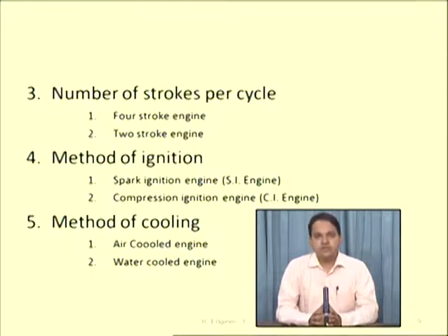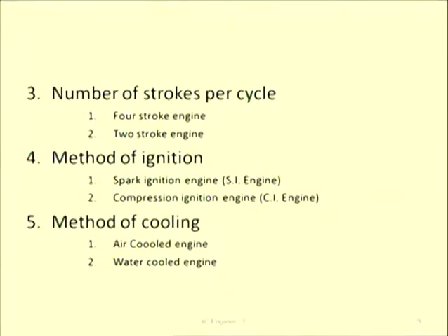4-stroke means the engine will take fuel in, then the combustion process will take place, heat liberation will take place, and then we utilize it into mechanical work. In the 4-stroke engine we have suction, that is inlet, where fuel and air mixture is taken in case of petrol, and in case of a diesel engine, diesel will be injected. Air will be taken into the engine cylinder. The second stroke is the compression stroke, so the fuel will be compressed at higher pressure.